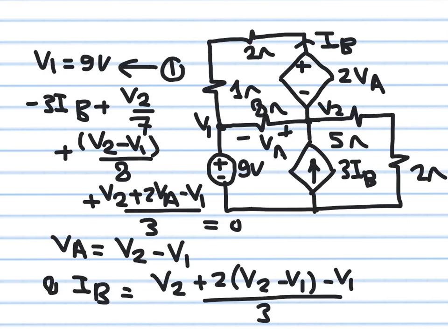So in this slide, I made the current source open circuit. Okay, so this branch disappeared. It's not there because there is no current flowing in it. So this is how the circuit now looks. I redrew the circuit, and now I will have to solve it using any of the techniques I learned before. If I take a look at this circuit, I notice that I have actually only two nodes, V1 and V2, and this ground. So I can apply nodal analysis the easiest.